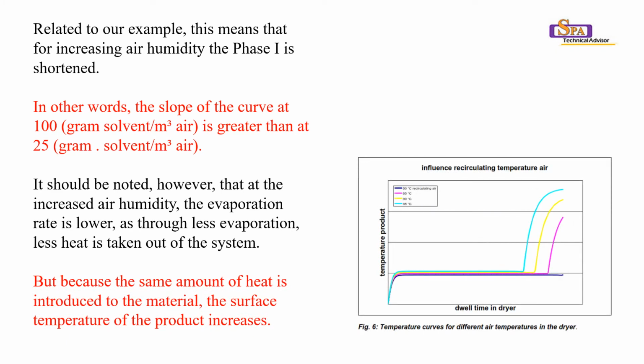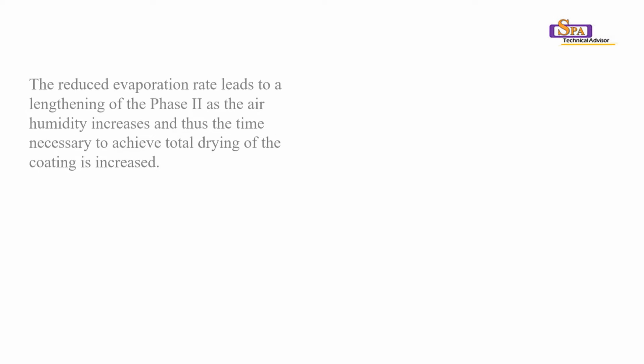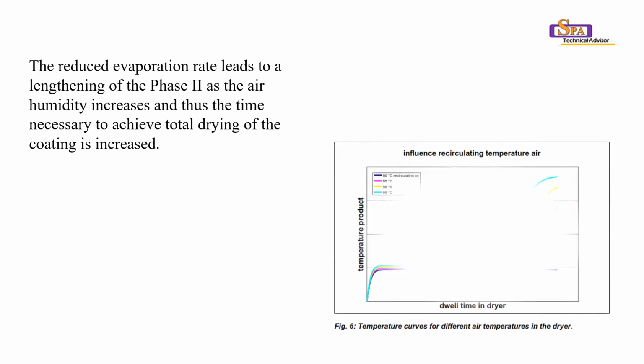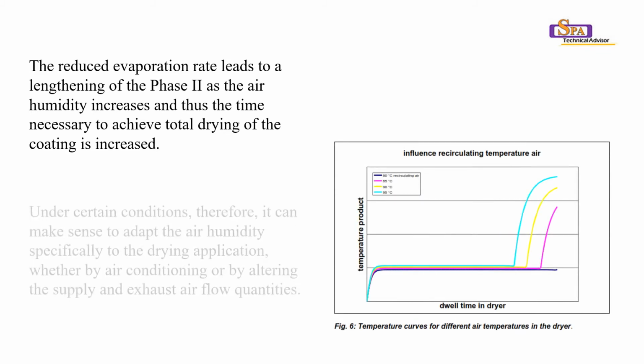Here is a chart, have a look again. The reduced evaporation rate leads to a lengthening of the phase 2 as the air humidity increases, and thus the time necessary to achieve total drying of coating is increased.